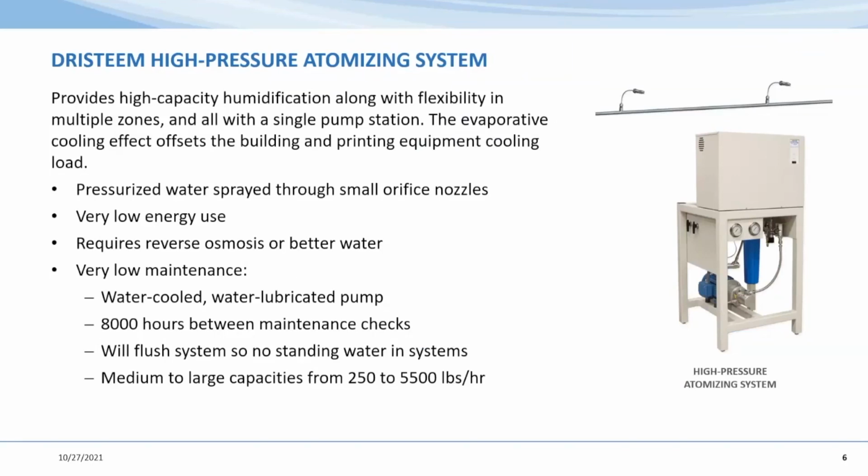That excess heat, typically from grow room facilities, can come from dehumidification equipment and their heat offset, or the lighting system. Even LED lights have a heat gain portion, obviously a lot lower heat into the environment than traditional lighting sources, but that heat can be utilized. And this technology also cools at the same time that it humidifies. It's one of the adiabatic technologies, and this can be advantageous for facilities that do have heat gain.